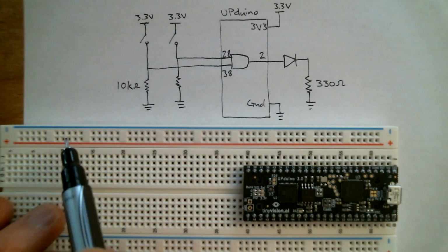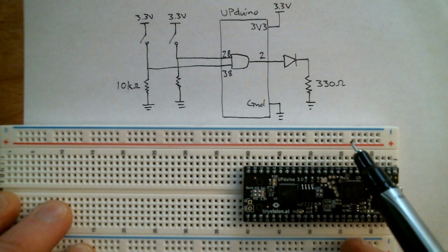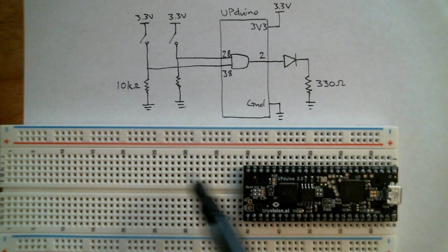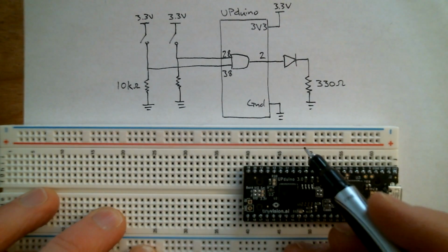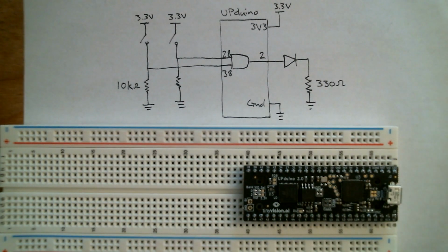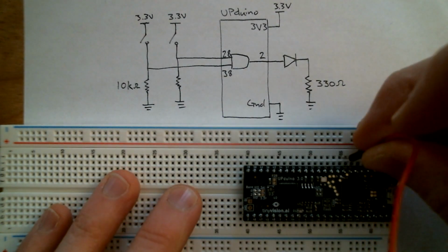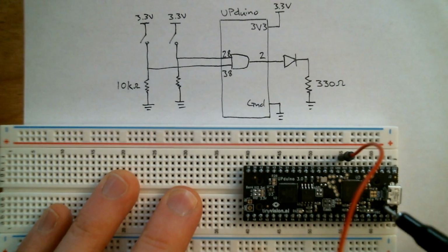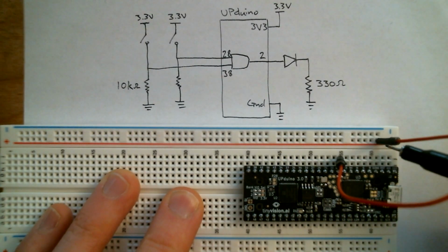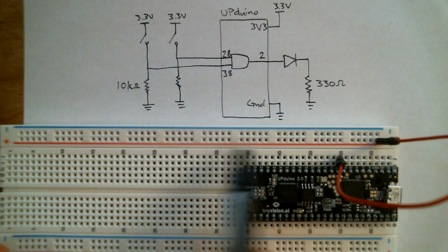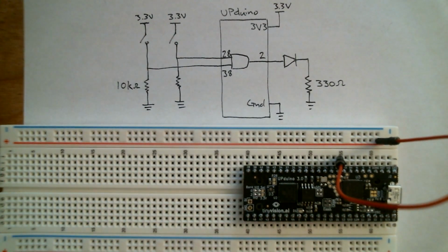The other thing to know is that these long rails on the ends, one's labeled blue and one's labeled red, don't have any electrical significance, but by convention we're going to use the blue one for ground and the red one for power, so for 3.3 volts. That's because oftentimes ground and power need to be distributed to lots of places, and so it's really common to just wire that. So we'll take this to the 3.3 volt pin and we will jump over to the power rail. And now anywhere on this rail we can use to get 3.3 volts.